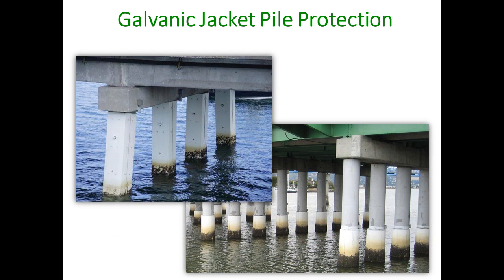And once the concrete is cured, you're going to come back and just remove the jacket, and you're going to leave this fiberglass stay-in-place form there. And as the tide goes up and down, you're going to have this seawater in there that's going to keep this jacket activated. It's going to create an environment in there that's going to be a nice electrolyte, and so you're going to have a significant amount of current that's present to protect the piles.